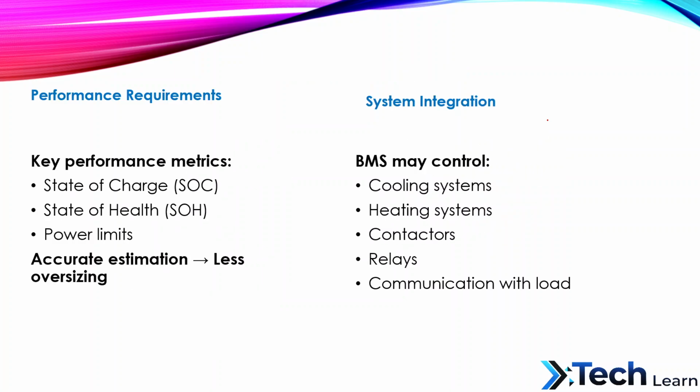Now coming to performance requirements, a modern BMS must provide accurate SOC, SOH, and real-time power capability. Accurate estimation allows the battery to operate closer to its limits without compromising safety. This reduces system cost and improves performance. Then how are we going to integrate this into the system? In advanced systems, the BMS does more than monitoring. It controls thermal systems, contactors, and safety relays, and it also communicates with the load device to dynamically manage the power.